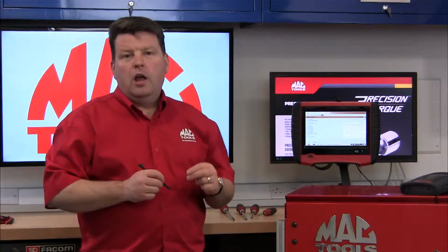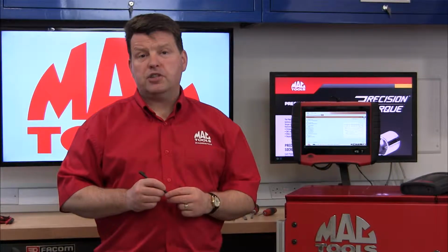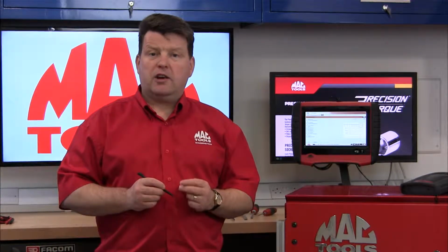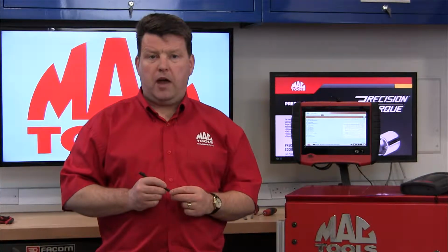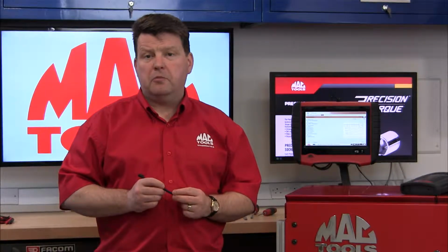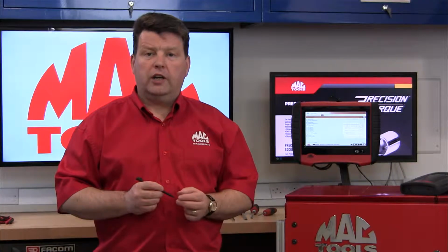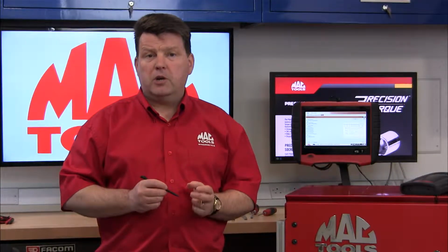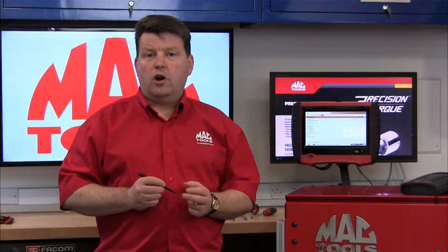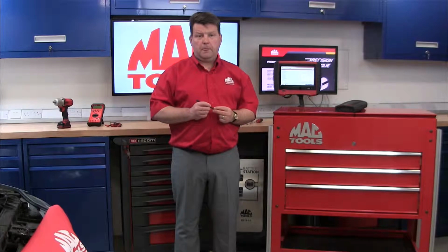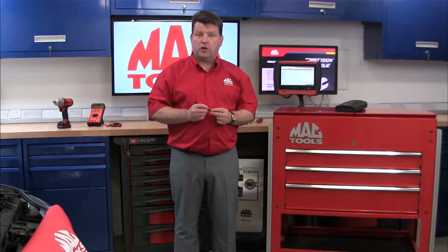Okay, we've got a diagram displayed, but why would I want to use one? It may be that I'm very familiar with diagnostic repairs and I'll use the diagram to familiarise myself with the system. I may need to check wiring integrity and this will tell me which wires to check. Or I might just want to find which fuse feeds a particular component. Let's go back to the diagram and take a step-by-step look at its construction.